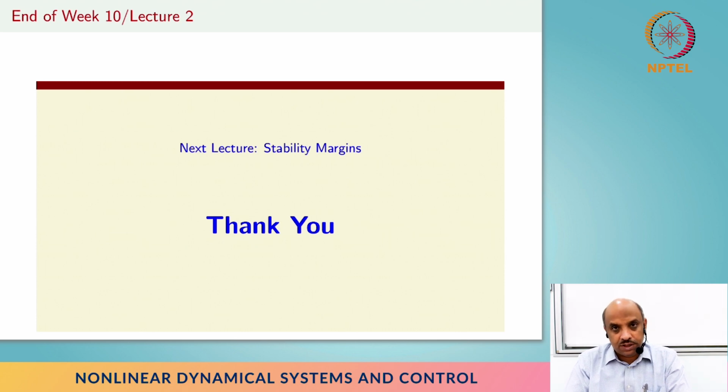We will first discuss a little bit about the importance of margins, and then the different types of margins, gain and phase, and how they are important in various scenarios. We will also introduce the strange notion of disk margins, and then show that optimal regulators will eventually have all these things, right?